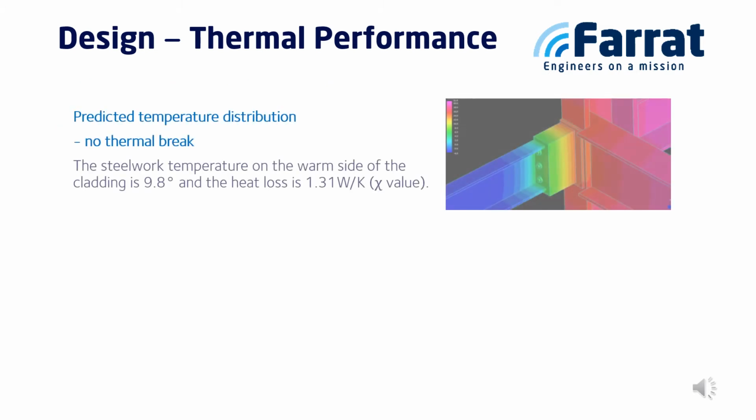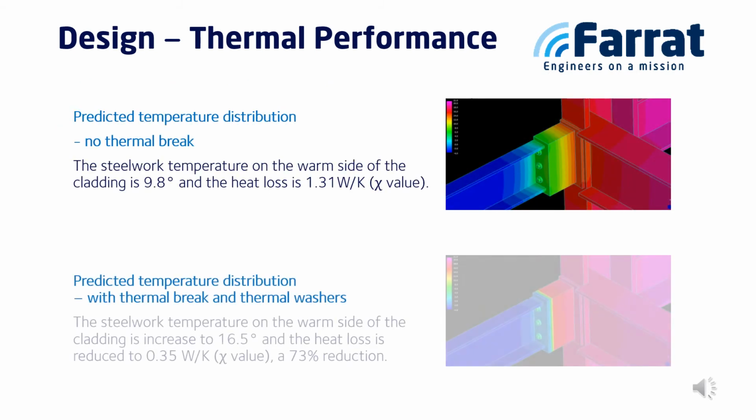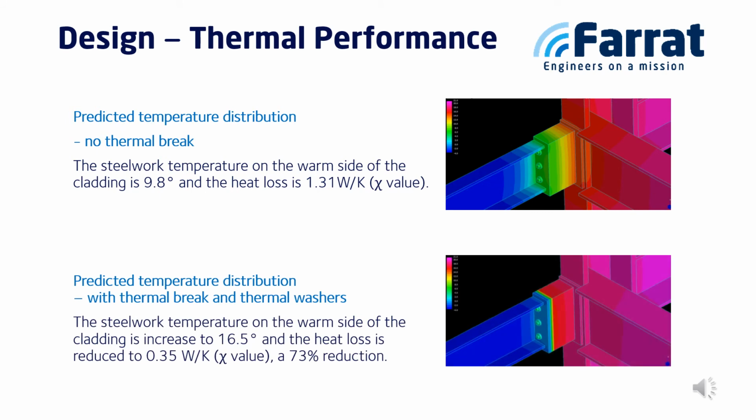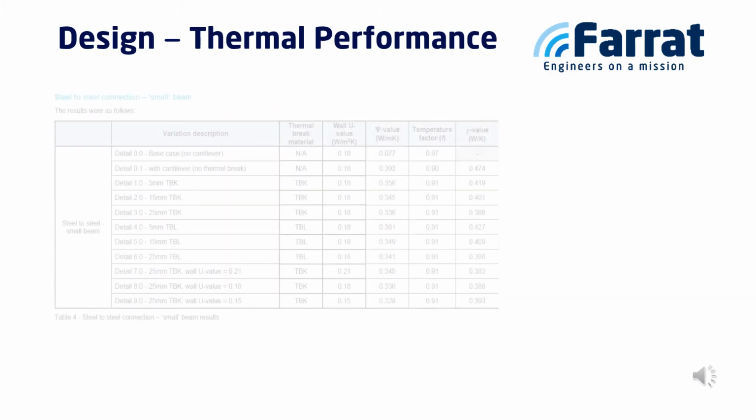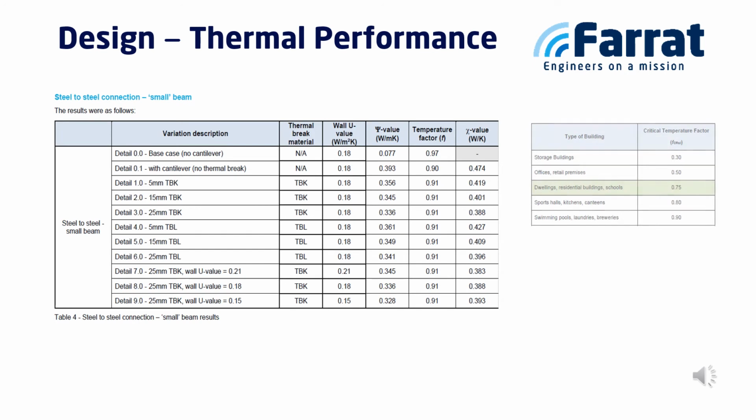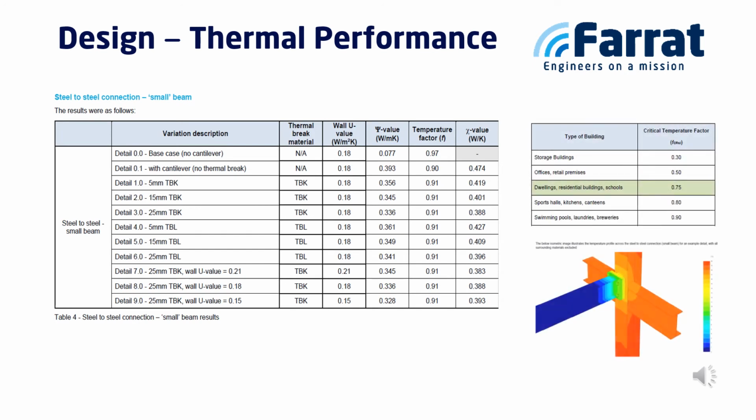Finite element analysis thermal modeling not only takes into account the direct connection of materials, but also the significant elements surrounding the connection. These surrounding elements have such an impact on the final result that they cannot be ignored in a simple calculation. In the absence of a full thermal model of the actual detail being used, typical details can be modelled and used as indicators of likely performance to specify materials that will meet the design requirements.